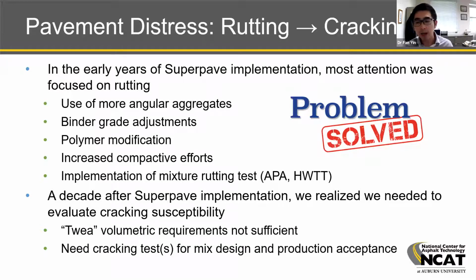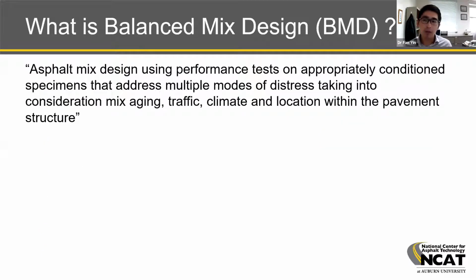In order to address the cracking issue, the state DOTs are now trying to tweak those volumetric parameters. But because of the limitation I mentioned earlier, VBE and VMA are volume parameters, and they don't indicate quality. Just looking at volumetric tweaks is not sufficient. So the industry has come to an agreement that we now need a more fundamental cracking test that can tell us how good the quality is, in terms of resistance to fatigue cracking and thermal cracking, for mix design and production acceptance. The need for performance testing leads us to the development of balanced mix design.